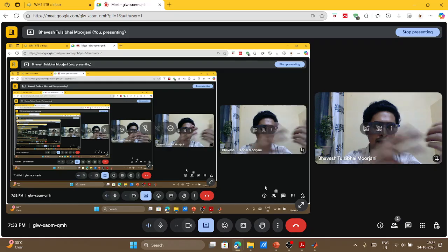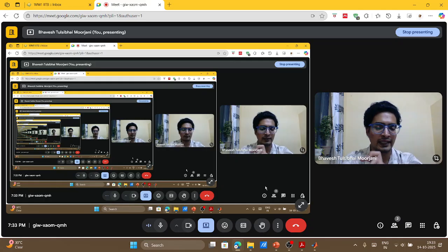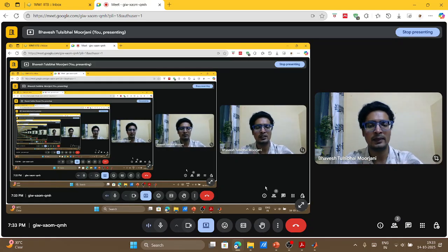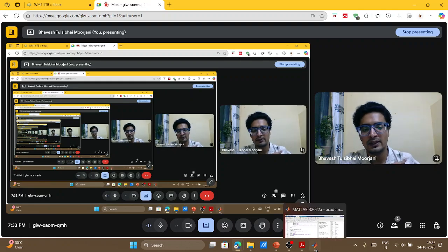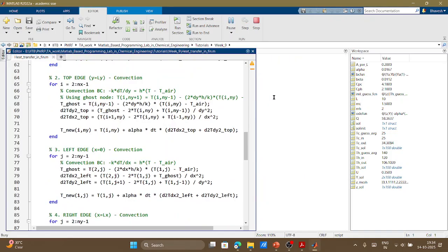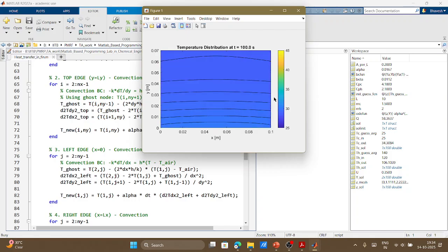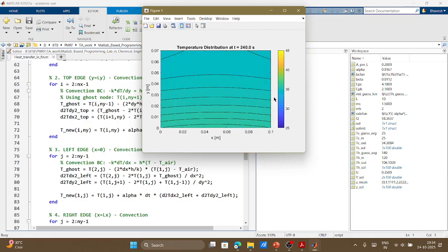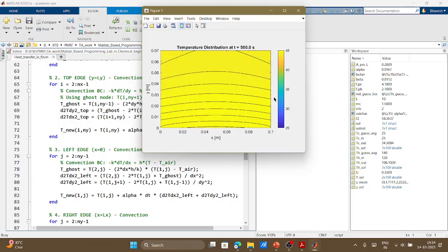So from the Taylor series expansion we know the finite difference equation. We can write the first order derivative and second order derivative with respect to the difference in the function value at x plus or minus delta h, right? So that concept we utilized and found out the values, and this is how that showed the variation in our temperature profile across the fin. So again, this is a very interesting problem. I hope you guys appreciated this problem, the kind of complexity it involved.